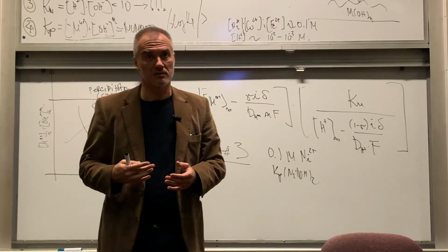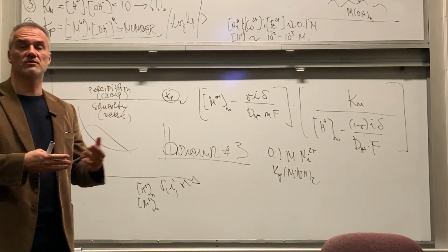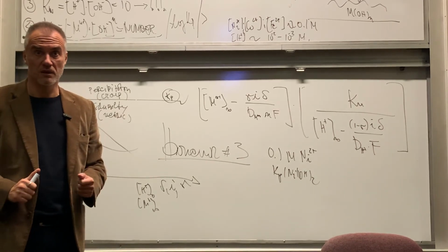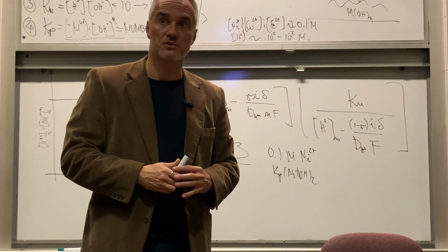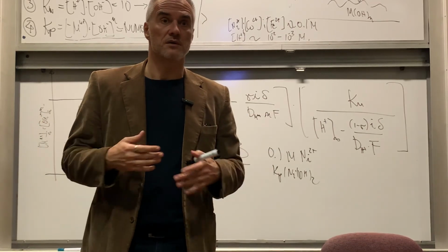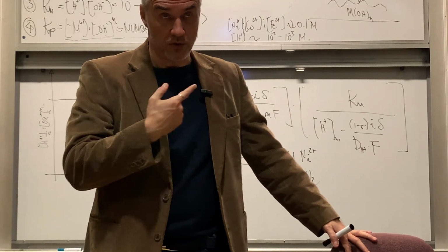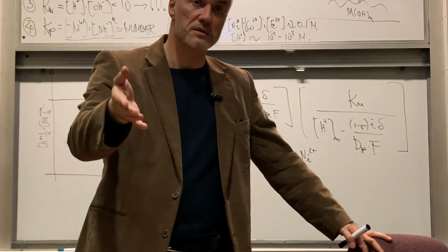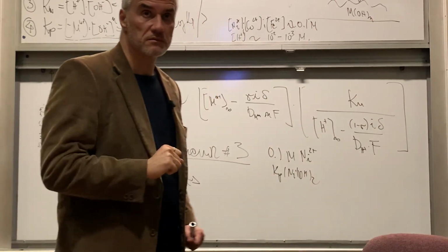That's usually not good, because you don't want to have a dominant reaction that is not related to metal deposition. That means you're wasting energy producing hydrogen instead of doing metal deposition. Now, in nanotechnology, not a big deal, but if you're doing nickel deposition, which is factory size, where the nickel metallization happens and serious electrical energy goes into the process, you're very wary about current efficiency. The higher, the less energy you need to deposit a certain thickness of the nickel, for example. So it depends on the application.